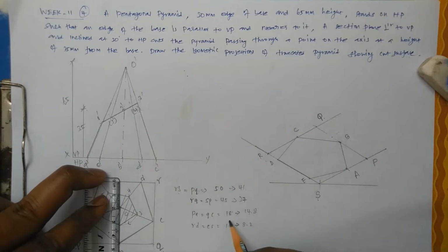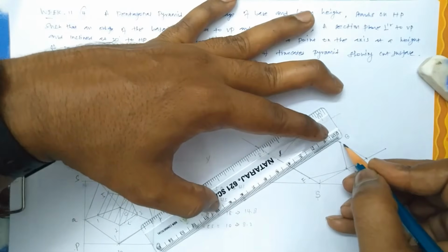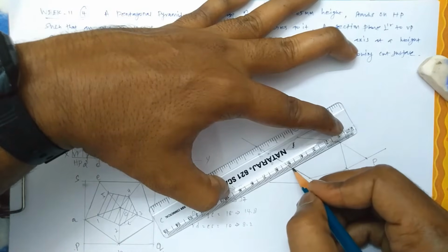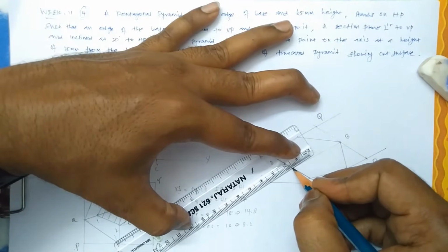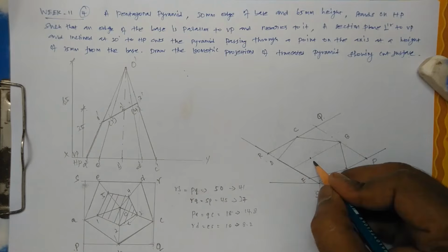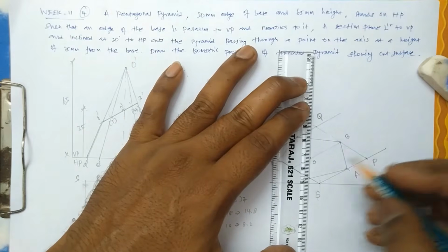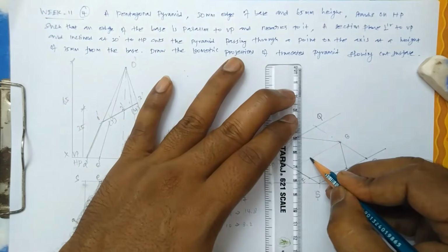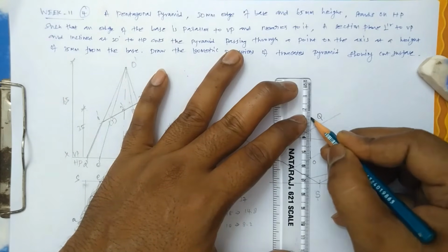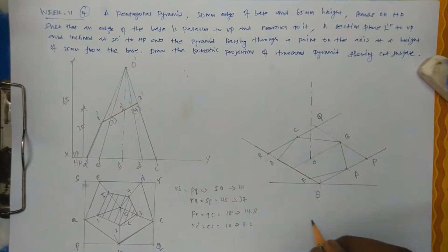Let us measure the O. Anyway, O is between these parallel lines of PS, from C, I think from B, so it may be placed in between. From here it is this measured distance, that is O. Anyway, it will be in the line. So erect a vertical line for 65 mm. That 65 mm is foreshortened to 54 mm, and now you connect all the edges.